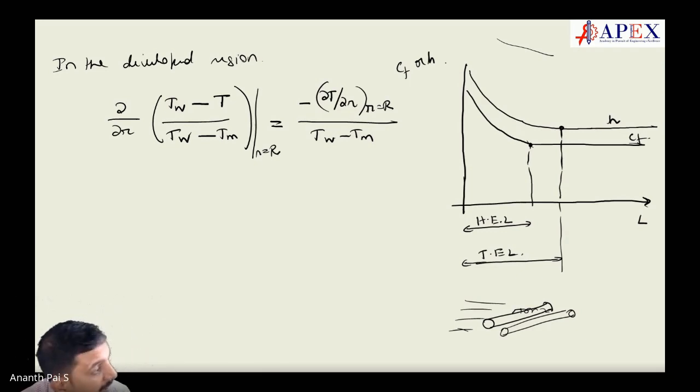Mean temperature changes. Why? There is heat transfer. It is like some part of the water dripping out. If it is insulated, it remains the same, of course. Very good. If it is insulated, it's an adiabatic pipe. Yeah, T mean is the same. Ti is equal to T out, because there's no way energy can go out. So Ti is equal to To in case of insulation. Correct. So that is how you have to think.